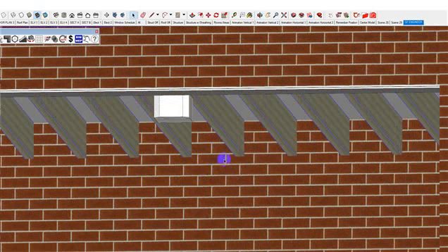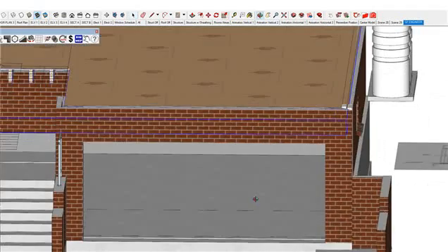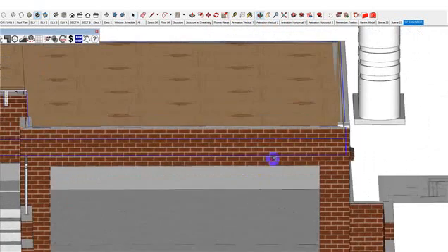this brickwork's too high, which means that essentially they wouldn't normally brick through joists like that. So what we need to do is drop the internal skin down and lift the external up. So I need to know the height of my joists so I can figure out how far to drop it down.